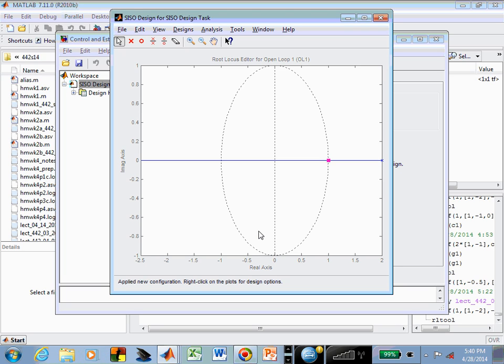for whatever reason. And so if you put all of this together right now, it's saying our closed loop pole would be right at z equal 1. And that's right on the stability boundary, and we probably don't want that to be there.